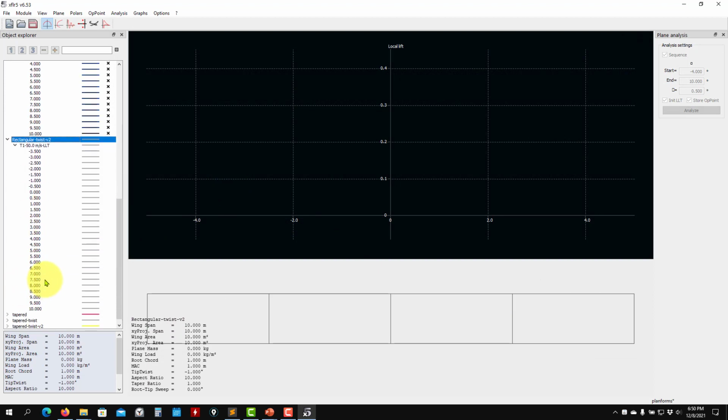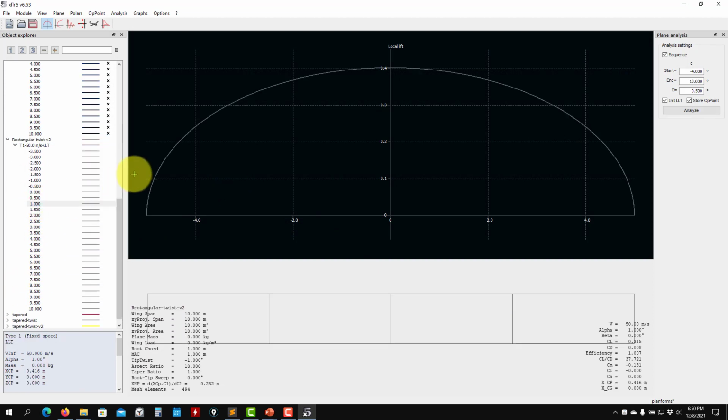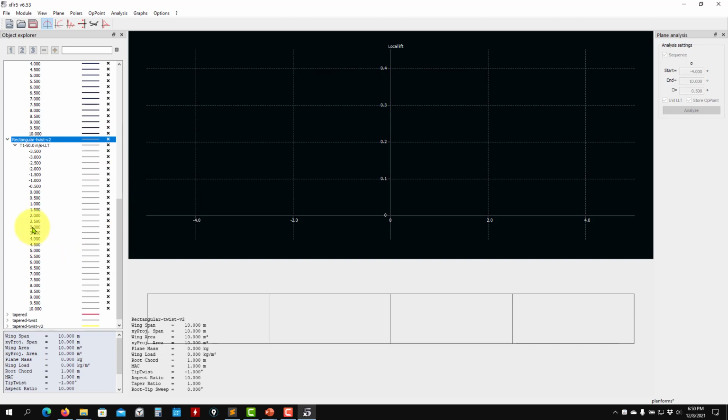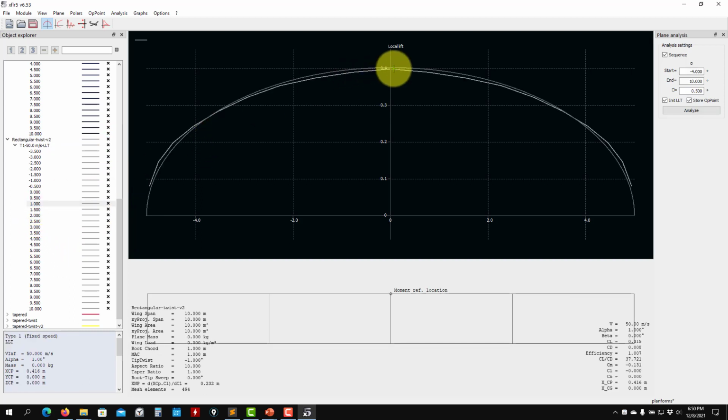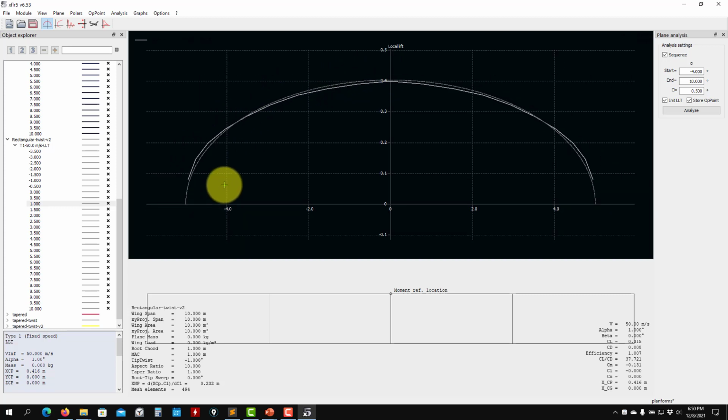So if I plot this result now, I need to visualize here 1, see that it is a very, very good approximation of an elliptical curve. So this is what we want at the end of the day, something close. It's very difficult to get it in the internal part. And this is one case, as you see in the slides, where the rectangular wing is the only one for which you can get this kind of result. When you have taper, it's very difficult to have it.